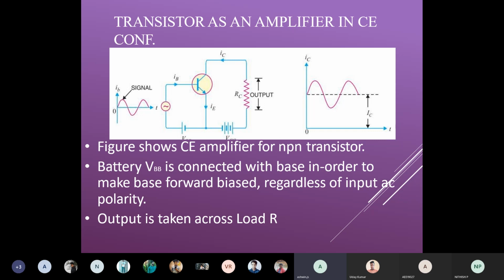If I'm having a very low base voltage, for example if I'm giving zero voltage, at that time the base doesn't have sufficient voltage to switch the transistor on. So the output will be very high.